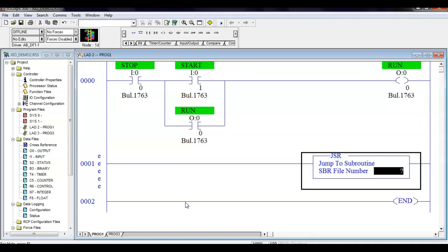So instead of trying to find the program that controls the carousel on the Festo line, instead of me going through 52 lines of code to understand, I might have a subroutine that says carousel control. On the Fanuc robot, it has one subroutine for every little move that it makes. So when we had the Festo, originally when we put the line, we put it over here. When we moved it over there, the floor is not exactly the same, and the robot missed everything. So I had to reteach every point.